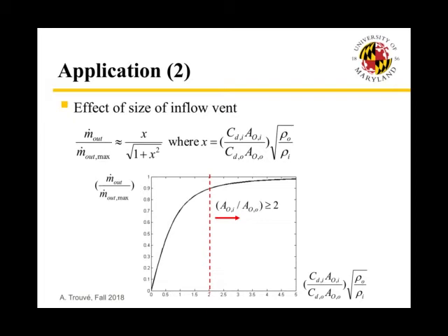This is a design criterion that you can find in the SFP literature and in standards: when you want to design a smoke control system using ceiling vents, you want the surface area of the ceiling vents to be large, and you want the surface area of the makeup air vents located at the floor to be twice as large. If you do this, the efficiency of your smoke venting system is above 90%.